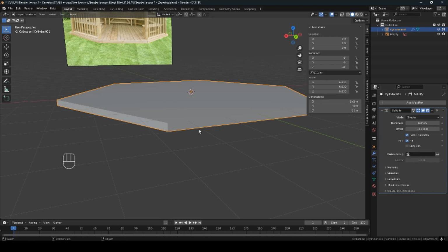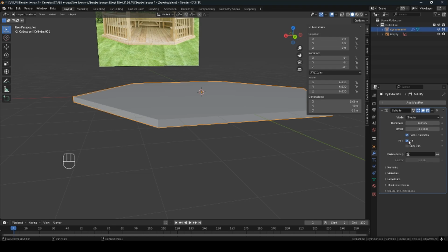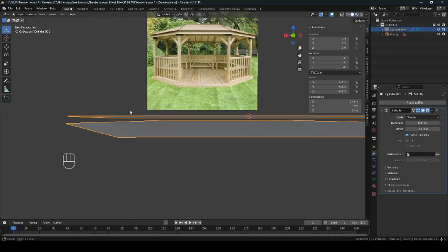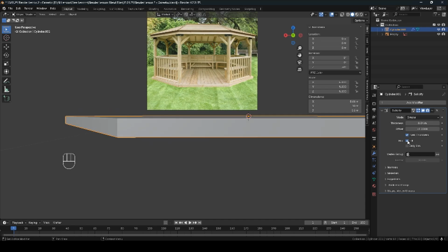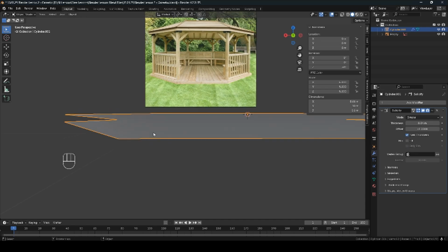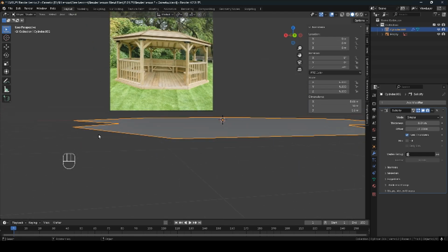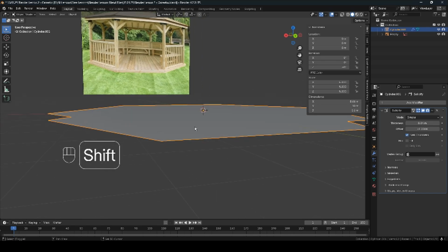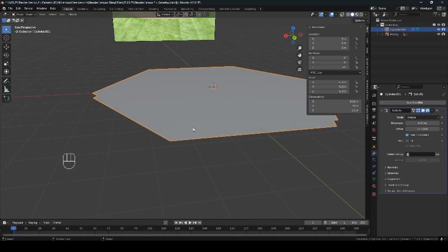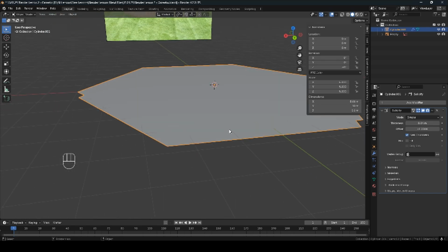We will even the thickness, even though, again, this shape's quite simple, so even thickness won't do anything. And fill rim, as you can see, that fills the sides in, on or off. This is very good if you're using planes either side for making leaves for trees. This is also a very, very good idea to do that as well, so you can reduce the poly count.